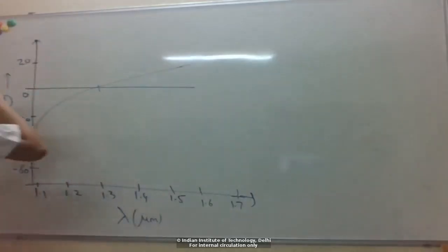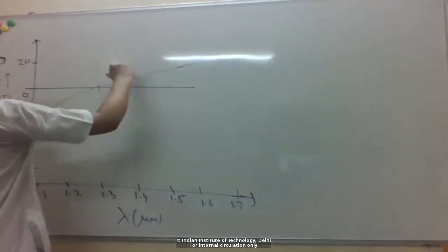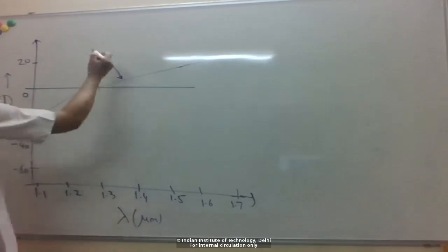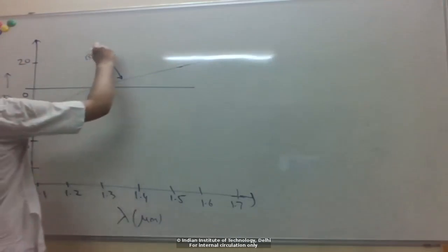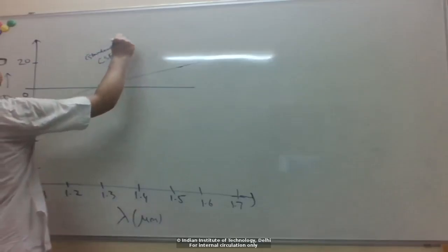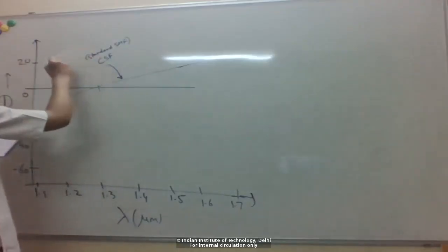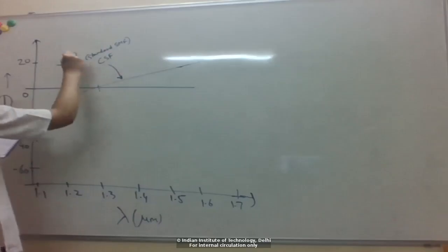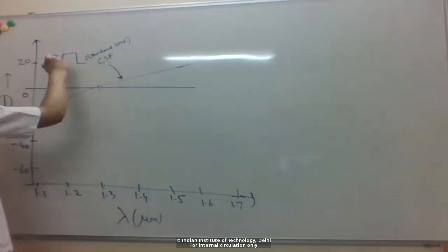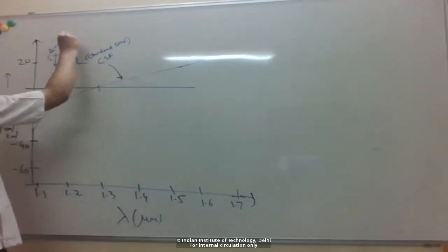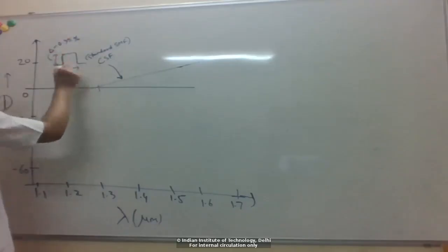Right, so this is what we call the conventional single mode fiber, or the standard single mode step index fiber, like SMF 28 that we discussed, right? So this has a refractive index profile like that. Again, this refractive index contrast is about 0.35%, the core diameter is about 9 micron.